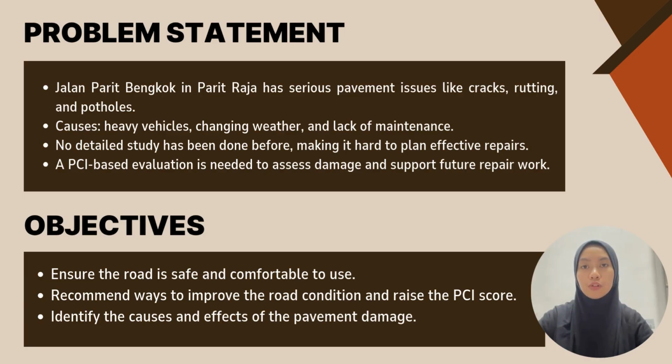So for the problem statement, Jalan Parit Bengkok in Parit Raja has pavement problems like cracks, potholes, and rutting. This is mostly due to heavy vehicles, changing weather, and poor maintenance. No proper study has been done before, so it's hard to plan repair. We need to use PCI to check the road condition and plan the right solution.